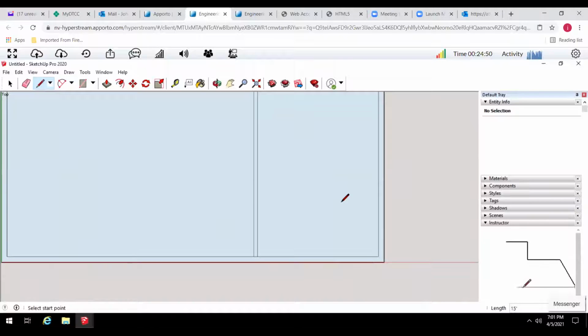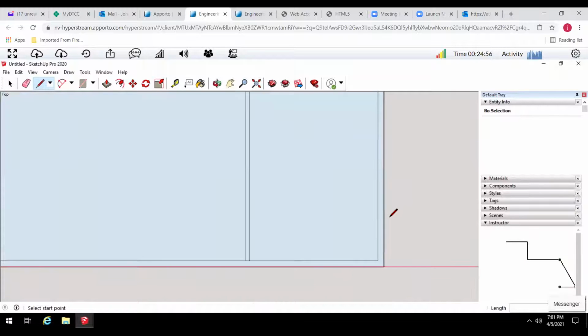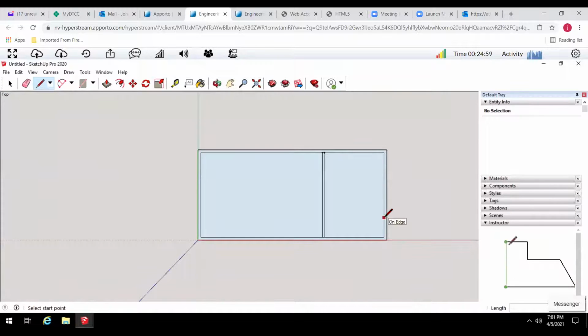Now I have the interior dimension. Let me roll it back out of the living area. Notice I am not showing any door openings, nor any window openings, because that's going to be done when we actually extrude it. Right now we're just adding walls, no openings, just walls.